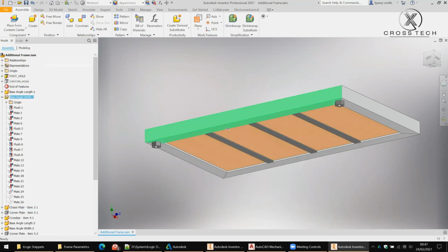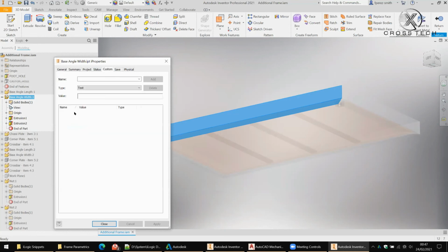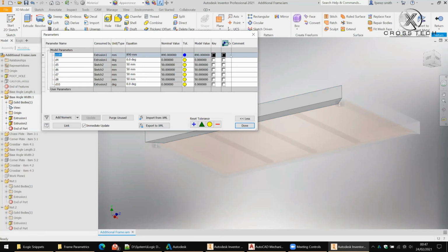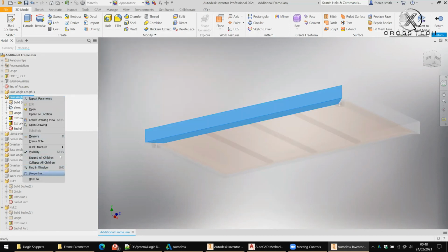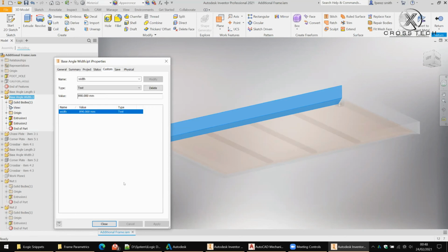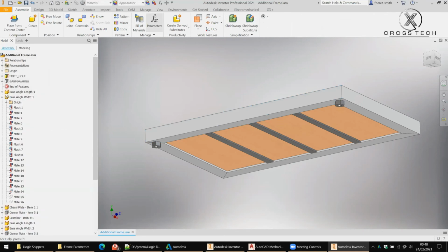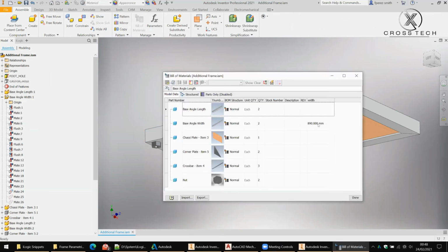Now, if the parameter is exported, it will show up here. So to export a parameter, we'll come along here and we'll click this little button. We can either click this button or we can actually add in a little bit of code that forces an export. Either works well. And hopefully it's already done it. There we go, with 890. Lovely. Now, if we have that parameter, well, I shouldn't call it a parameter anymore. It's a metadata, an identity. We can add it to the bill of materials. And here, if it exists in the part, it will show up in the bill of materials.